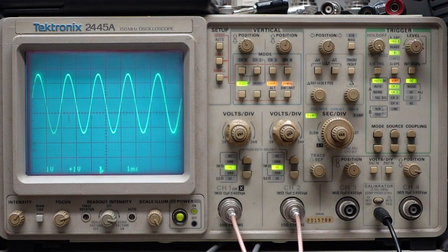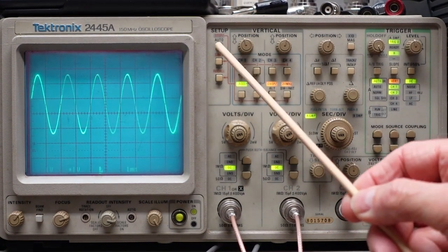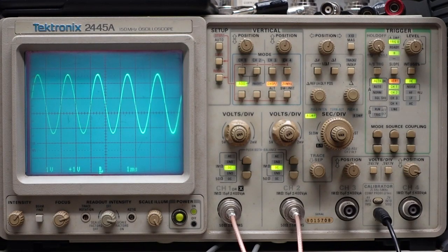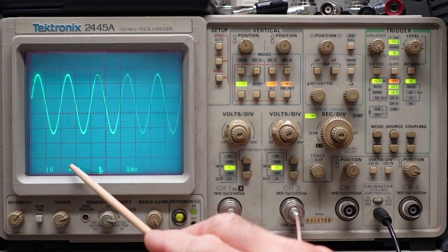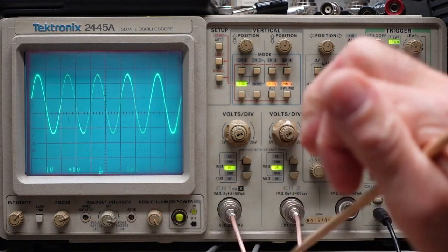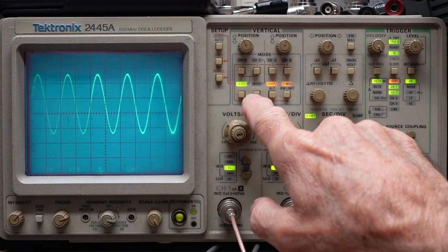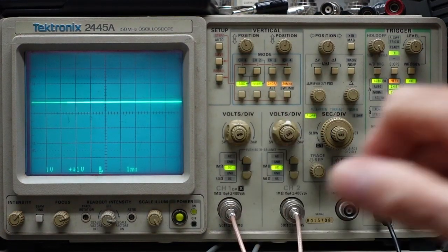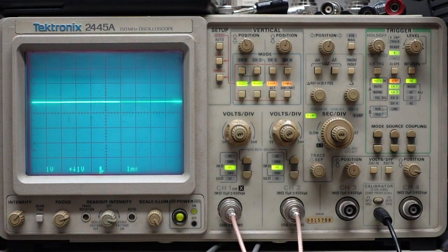Now, if you add and invert both channels, what do you think you'll get? Well, if we add them together, we get channel 1 plus channel 2, but invert only affects 1 channel. And indeed, if you look at the display here, you can see our add is over here, and when I hit invert, this should go to a flat line. Now, why would that happen? Remember, if we're adding one and adding the inverse of the other one, it'll simply cancel out.